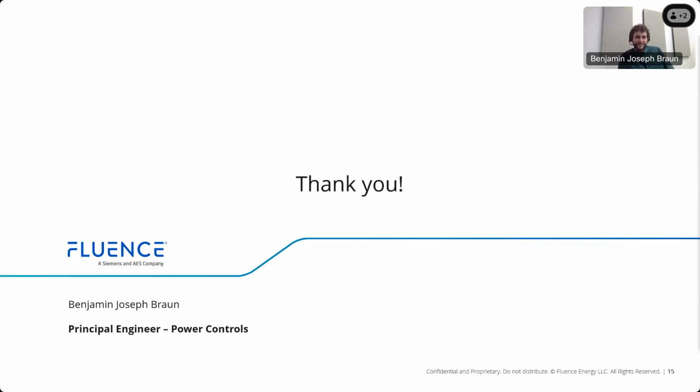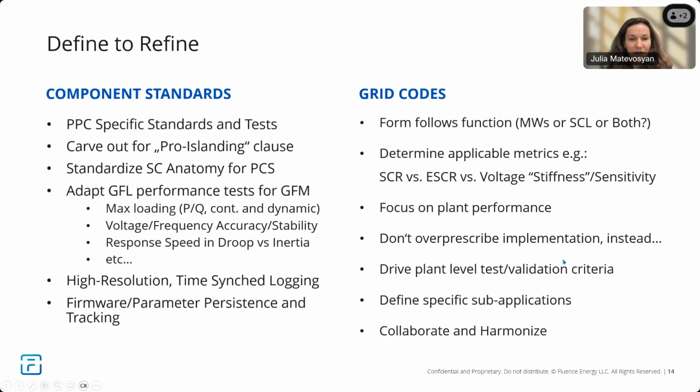Sounds good. So the next question is, do you have any suggestions or ideas of how to evaluate grid forming IBR contribution to system strength, something other than short circuit current contribution? You mentioned, say, in Australia, there is this consideration of deterioration of system strength from an IBR resource that connects. But do you have any ideas for how to value grid forming plants' contribution to system strength?